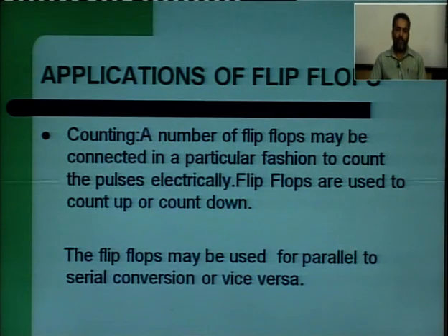Now, counting. A major application of flip flops is the counter, that is called counting, meaning a number of flip flops may be connected in a particular fashion to count the number of pulses electrically, to count upward or to count downward. In this case T flip flops are used, because the T flip flop toggles, meaning it changes its state with every clock pulse. The flip flop may also be used for parallel to serial conversion and vice versa. This is also an application.